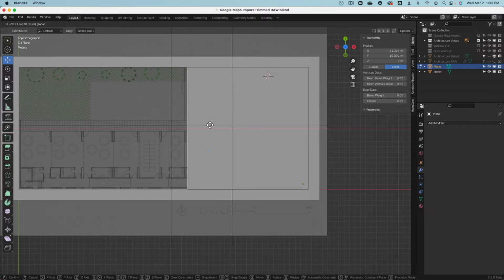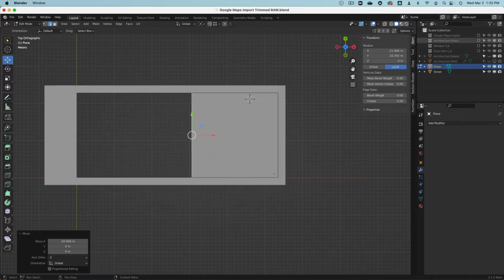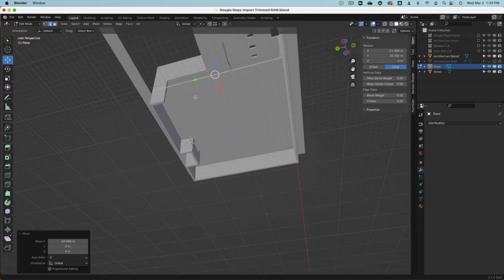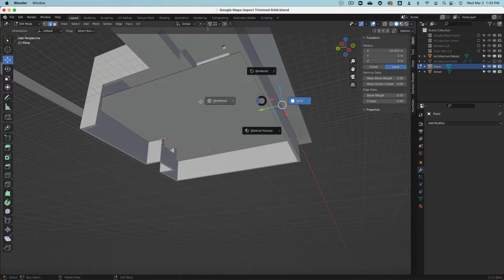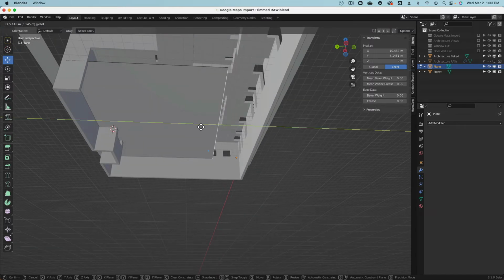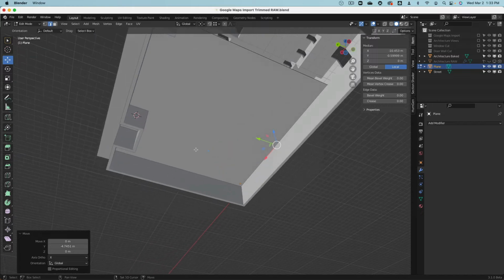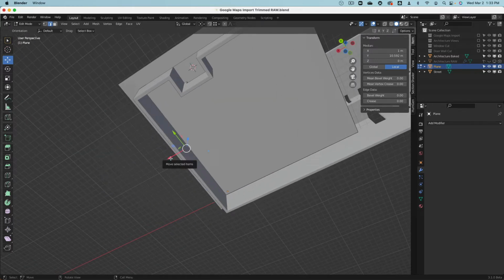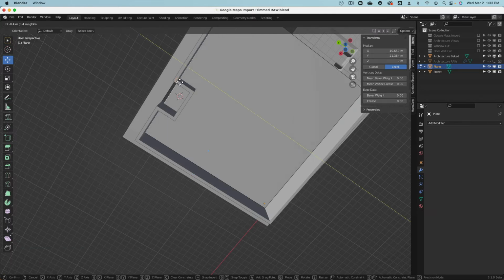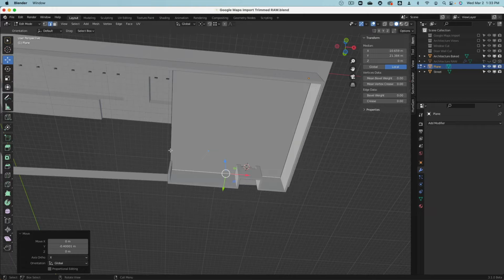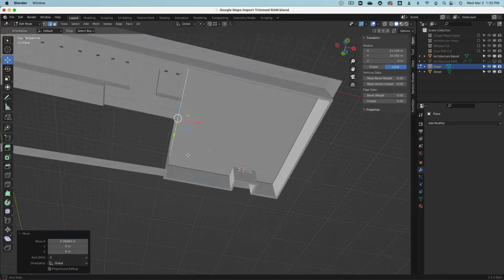It has to go to there. Because what I need to do now is, first, every edge has to be moved backwards a little bit. You see this edge moved back, and hold Control and snap to there. Then if I click there and this is selected, move, hold Control, there, hold Control, there. And then this one you hold Control to there.